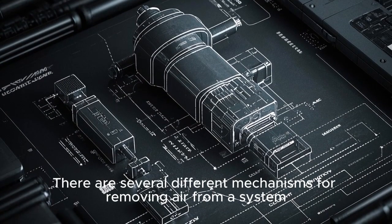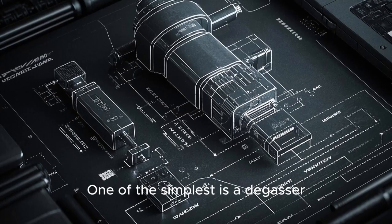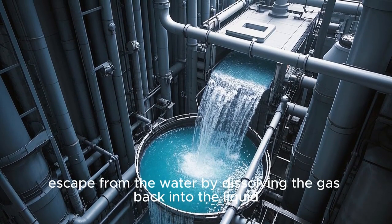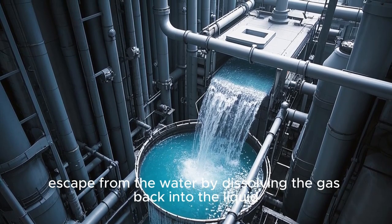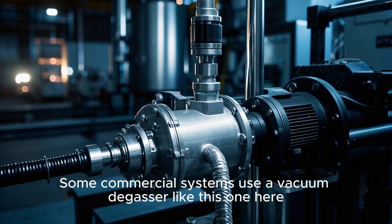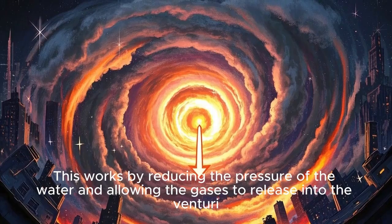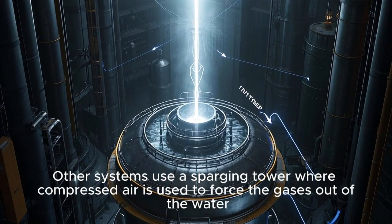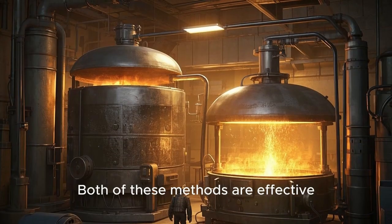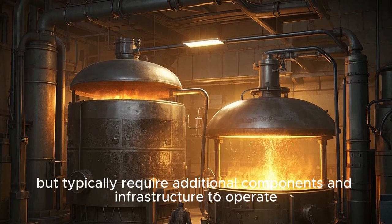There are several different mechanisms for removing air from a system. One of the simplest is a degasser. A degasser uses a packed tower to allow air to escape from the water by dissolving the gas back into the liquid. Some commercial systems use a vacuum degasser like this one here. This works by reducing the pressure of the water and allowing the gases to release into the venturi. Other systems use a sparging tower where compressed air is used to force the gases out of the water. Both of these methods are effective but typically require additional components and infrastructure to operate.